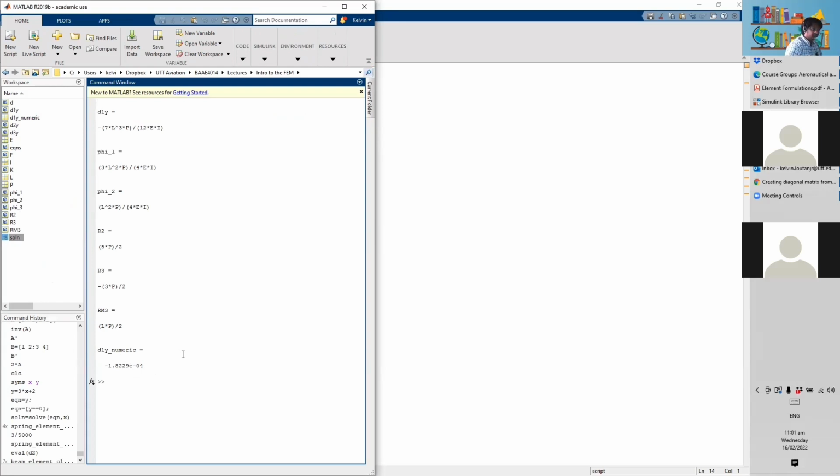Right, so that's the nice thing about doing maths like this, the signs take care of everything. So you don't have to think too much about whether it's in this direction or that direction, even with your bending moments and your shear forces. This, for example, is our bending moment because that's a moment at the end. R3, R2, all these things are shear forces, the same shear forces you would have learned in strengths last year. Substitute P into this and you'll get your shear force at this point.